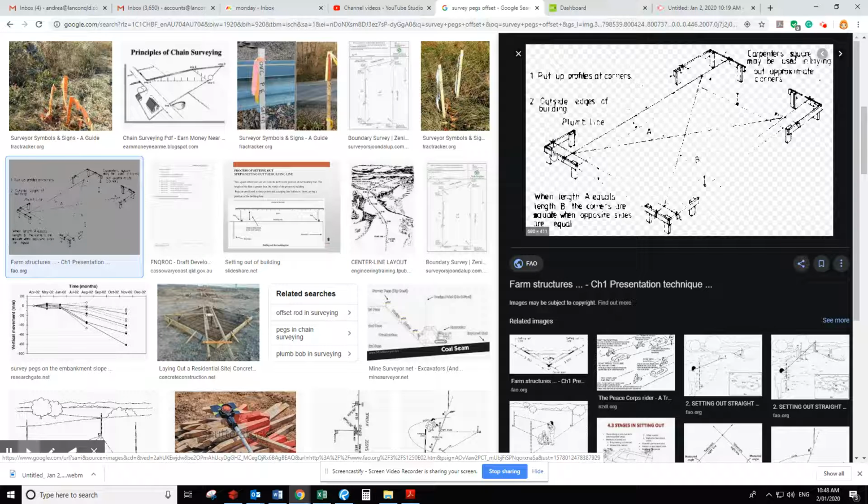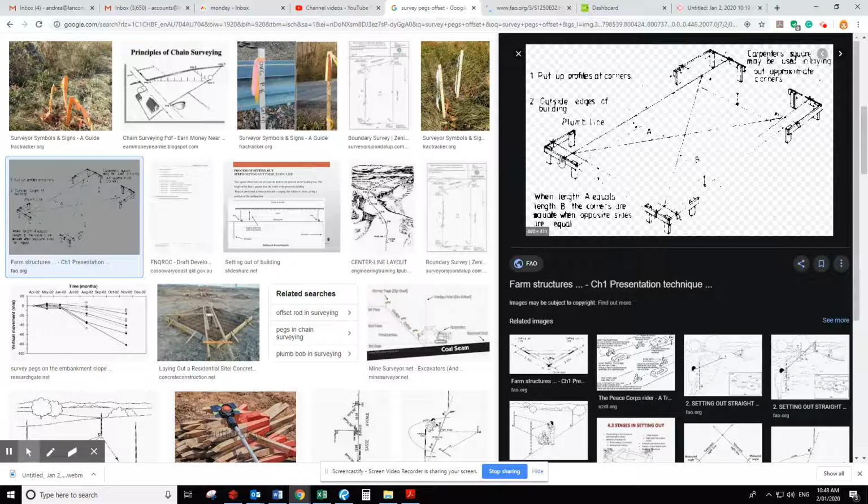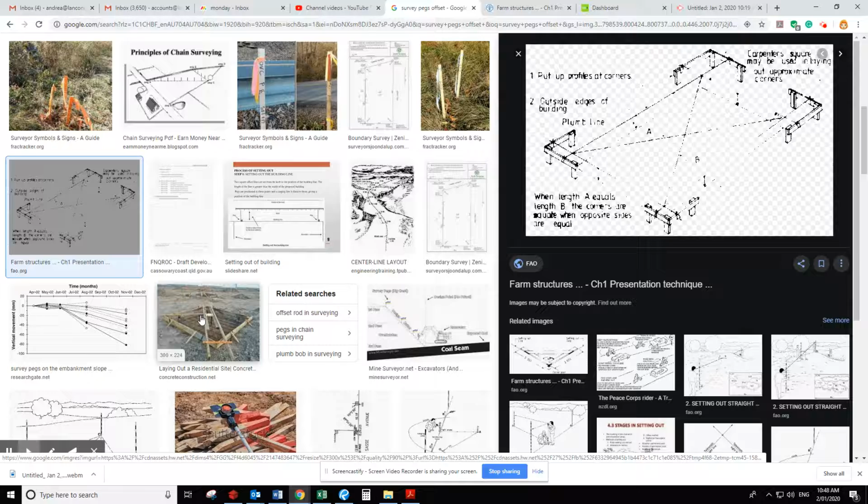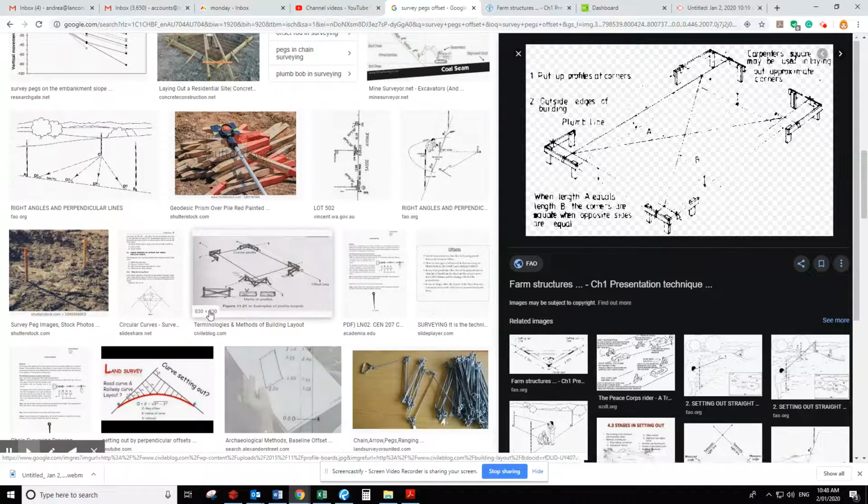They wouldn't actually put in the lengths of timber here, but they would put the pegs slightly further back from where they're actually required. So that would mark the corner of the building there, so that they could dig the holes and things like that for the main slab.